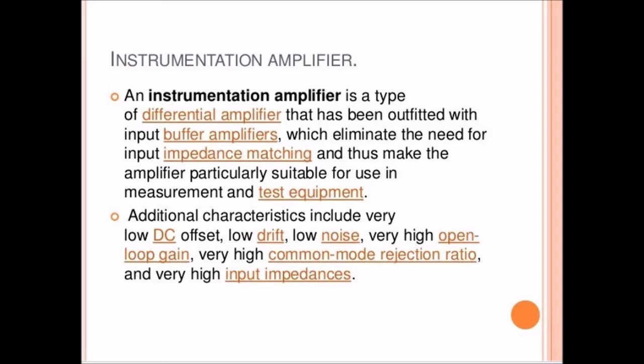This indicates that a differential amplifier cannot be connected directly to measuring instruments, because it measures the input with reference to the ground. The very important point is the reference to the ground. Whatever value we are getting at the output, V out, is with reference to the ground.